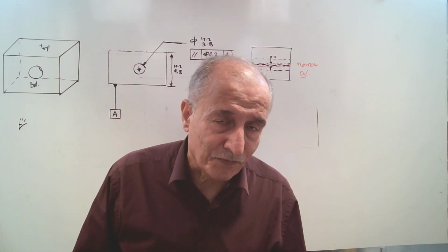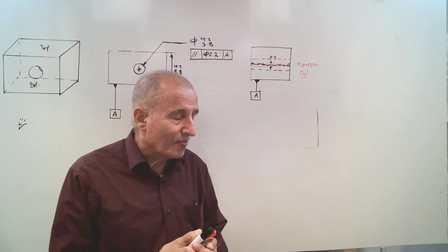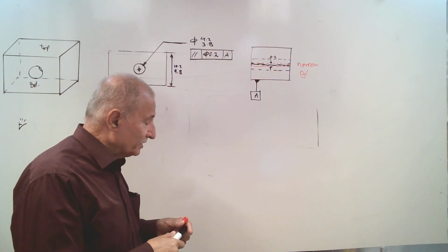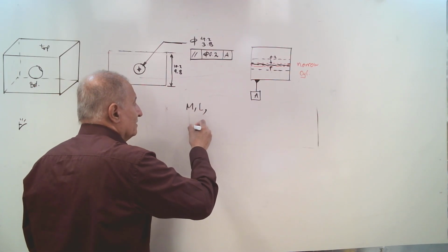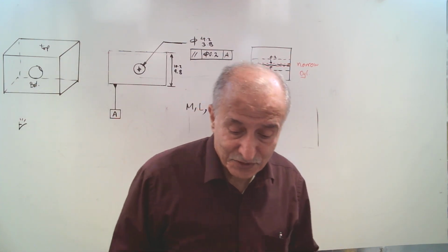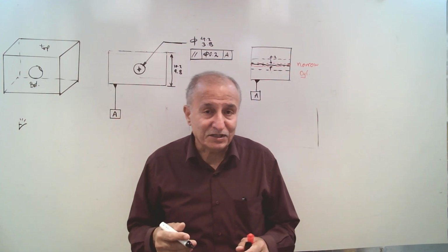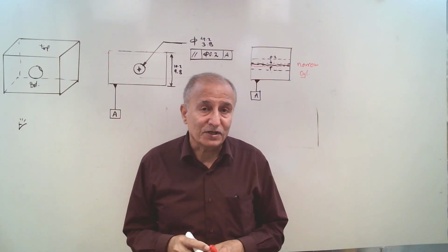We use the phi modifier for an axis because the zone is a cylindrical object. We can use modifier M, L, P, projected tolerance zone. Later in the position tolerance, we talk about this P modifier as well.